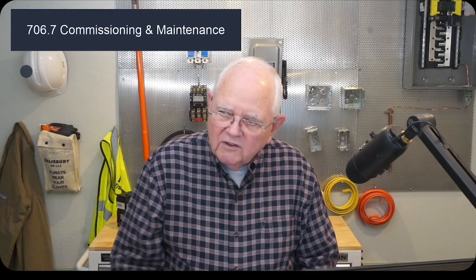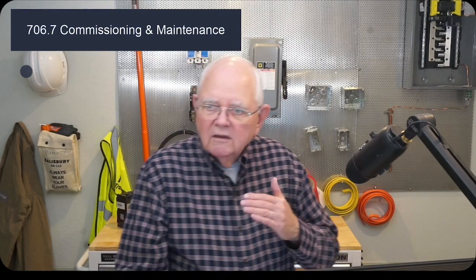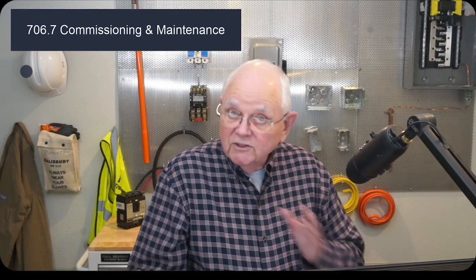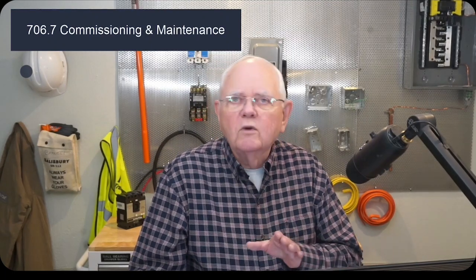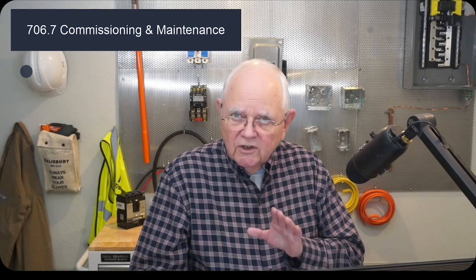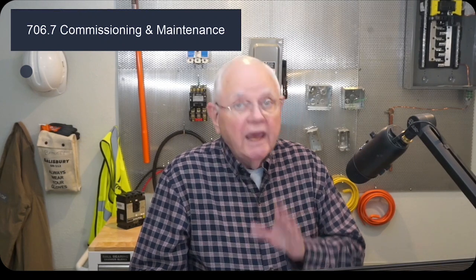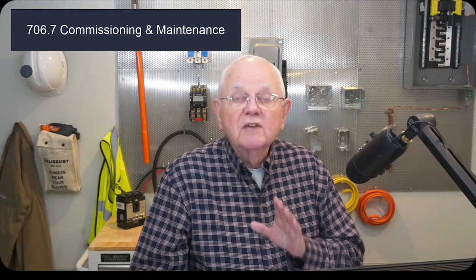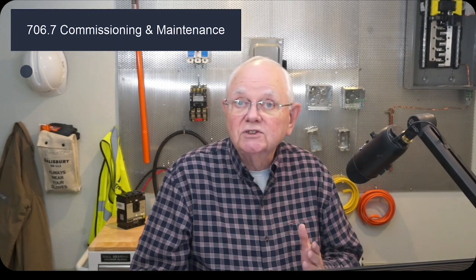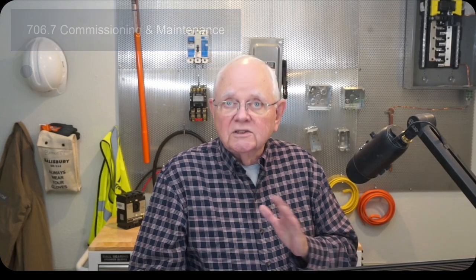706.7 talks about I have to not only maintain my energy storage system to keep it safe, but I also have to commission it. Now this doesn't apply to 1 and 2 family dwellings, but I have to go through a commissioning process. NFPA 855 once again gives me information on how to commission these energy storage systems, as well as other resources.